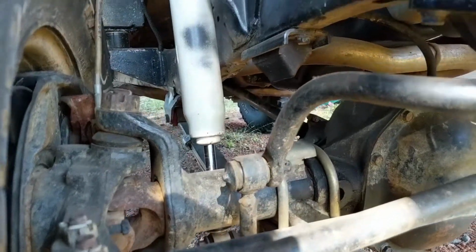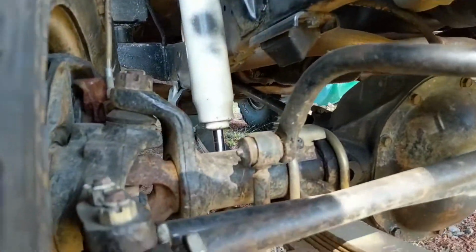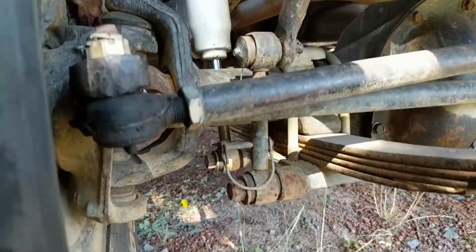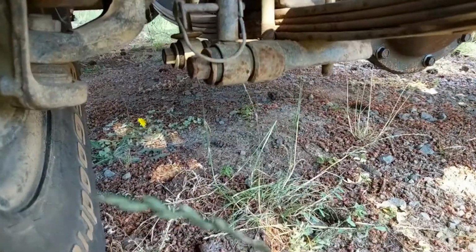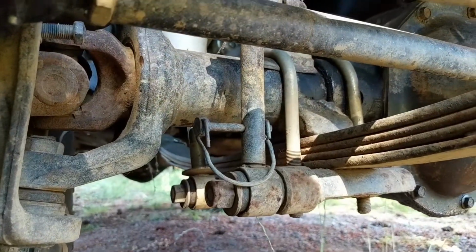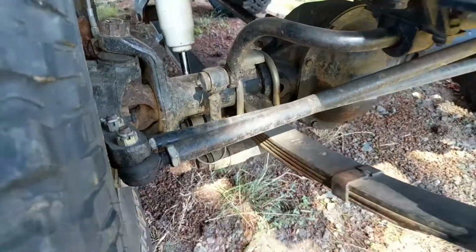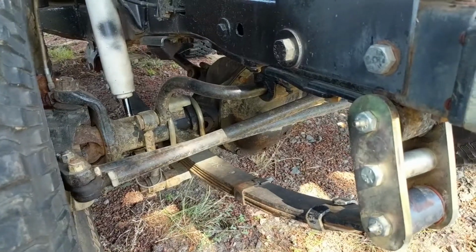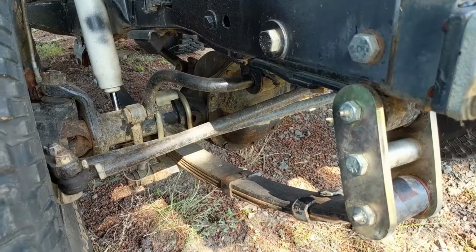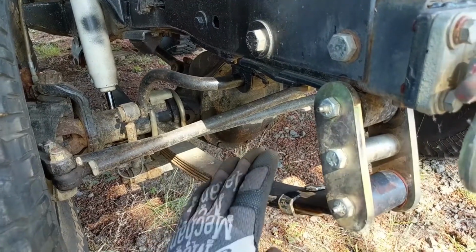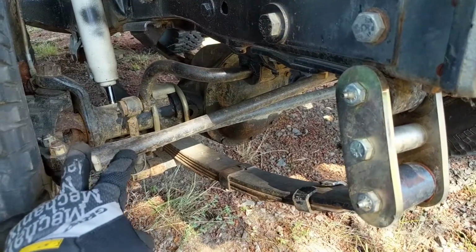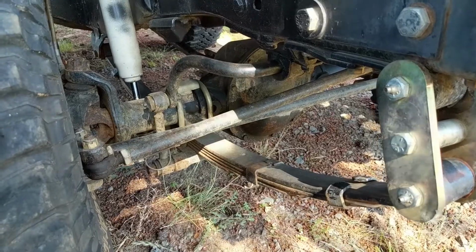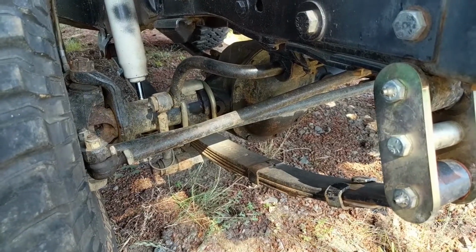And this end link, so remember, the bar is fastened to the frame of the vehicle, to the chassis of the vehicle. The end link comes down to the spring plate that mounts the axle to the leaf spring. Sprung components refer to parts of the vehicle that are supported by the spring. So here's our spring, and it is connected to the axle. The axle is in contact with the tires and the ground and is considered unsprung weight.